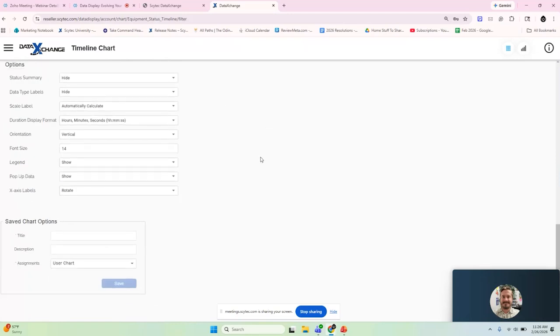And then once you're used to setting up all this filtering and getting the information that you want, you can come down here to your save chart options. This basically prevents you from having to do all the same filtering over and over. If you need access to this kind of chart every day, you can go in and title it, and then it'll populate out in the save chart options section. I will show you that here in just a little bit.